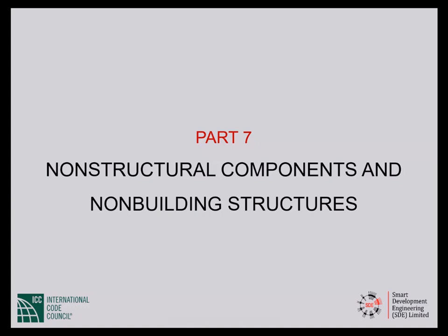Another question from the same gentleman: do we need to consider the 30% additional load in orthogonal direction described in BNBC for response spectrum combinations? What does that mean? When you are doing modal response spectrum analysis, if it is 2D analysis, it is the same thing.